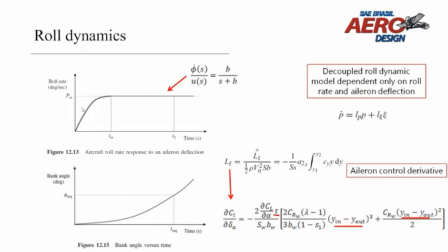a semi-trapezoidal wing, which has a rectangular section and a trapezoidal section, assuming the ailerons will be located only in the trapezoidal section. We can see that the control derivative depends on the aileron tau and the inboard and outboard positions of the aileron span. Then we can perform two kinds of solution for the aileron's dimensions, fixing tau or fixing the aileron span and applying the same iterative process that was applied for the elevator.